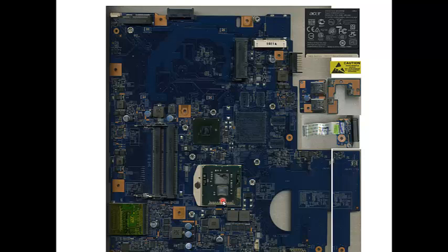Hi friends, today we are going to learn how to generate a CPU core voltage. A CPU core voltage is required for the CPU to function, and this voltage is approximately 0.8 to 1.1 volt. And actually the CPU core voltage is not only a voltage, it also requires some current, and that current is something about 20 ampere to 30 ampere.